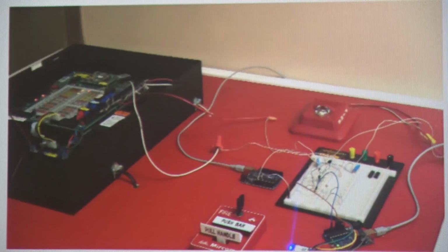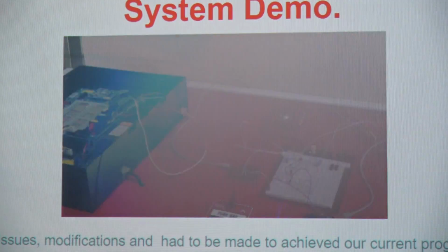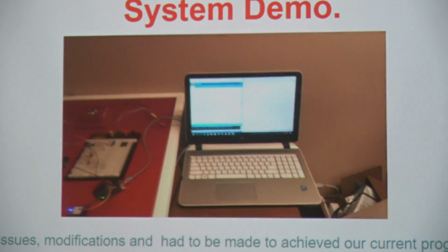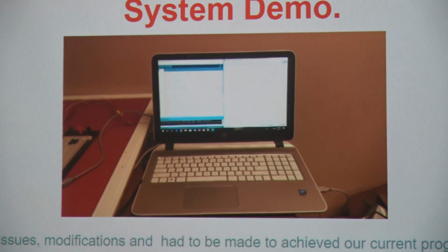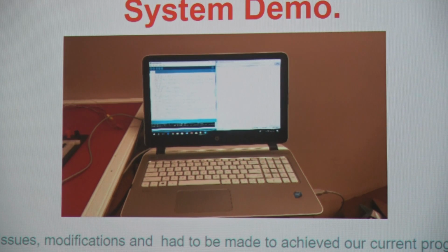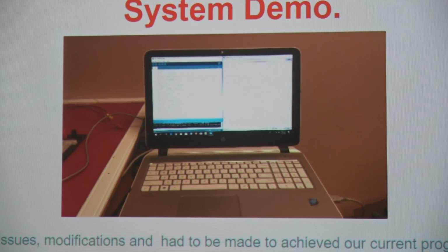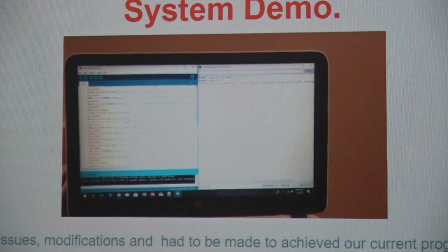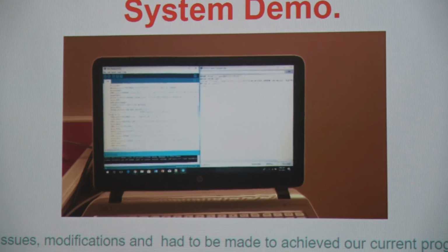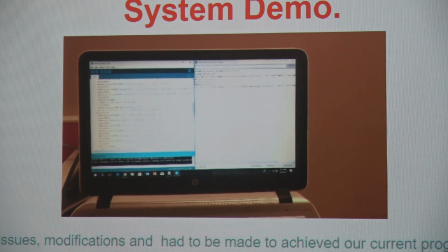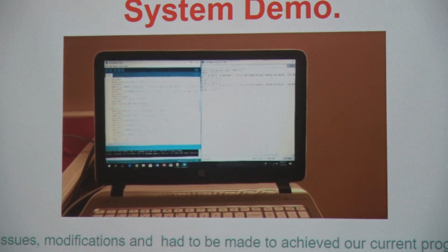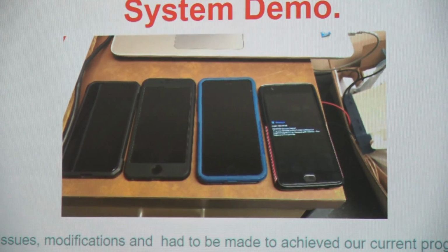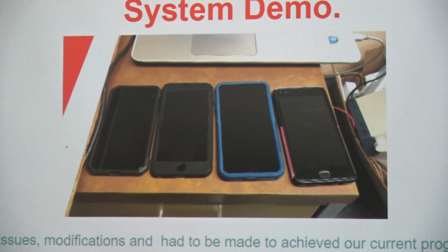So that was Nick pulling the handle. The voltage rises. The detector circuit then turns on the strobes. And then it starts initiating the code and sending out the text messages to the registered numbers. Being that it is just a 2G network, every time we tested it, not every phone got it; it would alternate. For some reason, Pav's phone always got the text message, because it was the first one in line for priority. But it would sometimes go first two and leave the last ones, and then sometimes it would do the first one and the last one.